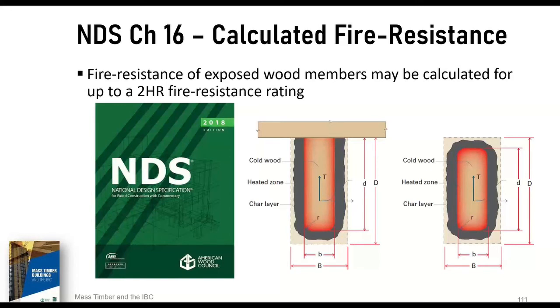IBC section 722.6, you'll find that also back in the IBC, but that's for built-up assemblies. That's not for the design of mass timber. For mass timber, you go directly to chapter 16 of the NDS.